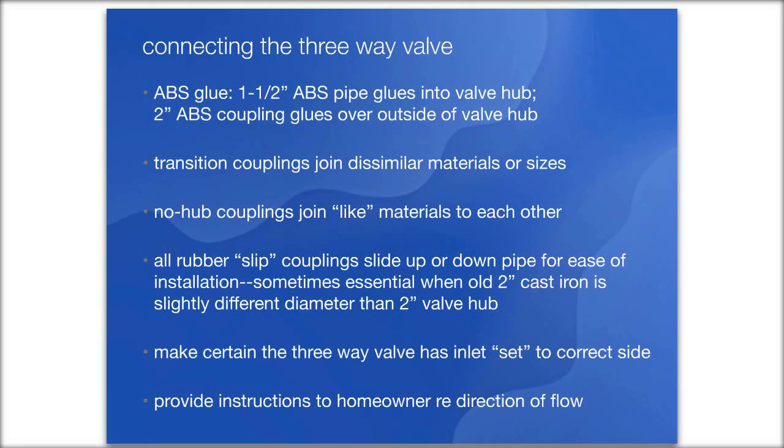So if you're using a Jandy three-way valve, you want to make certain that the three-way valve has been set so that the inlet is on the correct side where the incoming gray water is.